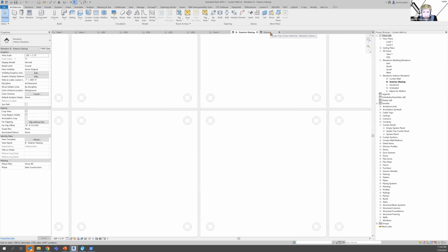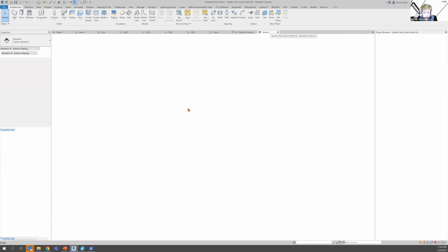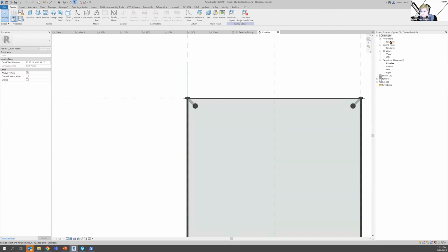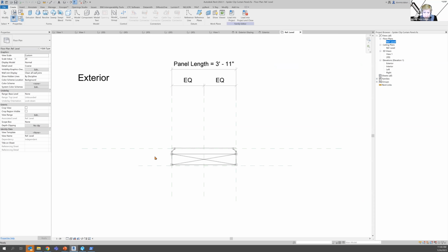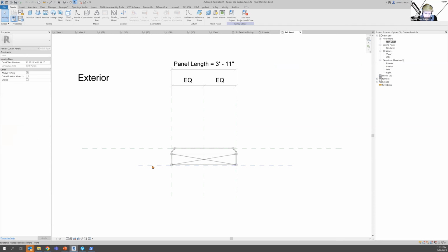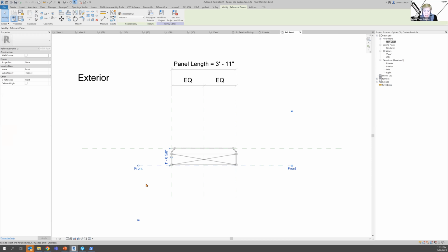And I'm going to be sending out the link to how to get to this guy right here. Also know with these, I added a reference plane back here because it didn't have one. You also want to know what your depth is, because you may want to make sure that you offset. Remember the 3 things about a panel? They have an offset, a thickness, and a material. So this one you may want to offset whatever your thickness is so that you have it offset from your structural members that it's going to be attaching to.